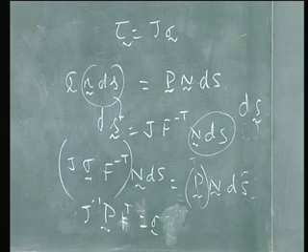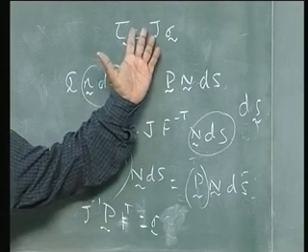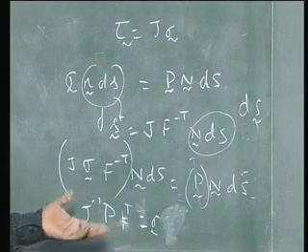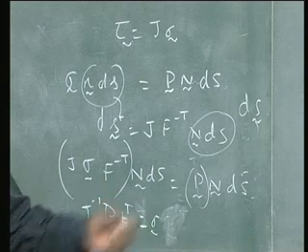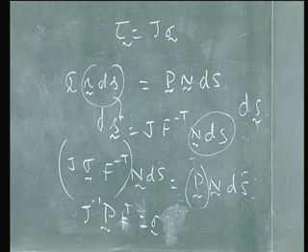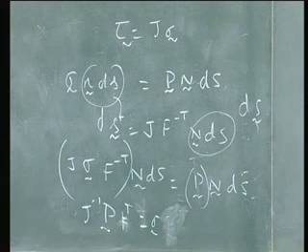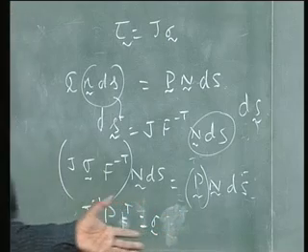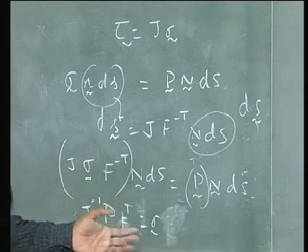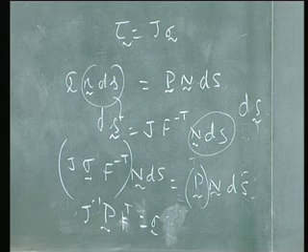Now, we know sigma is symmetric. By this definition, we know Kirchhoff stress is also symmetric. The question is whether the first Piola-Kirchhoff stress is symmetric. Symmetry has very important connotations in our computational techniques because you can save a lot of space and effort. So let us check whether the first Piola-Kirchhoff stress, the equivalent of a nominal stress, is symmetric.